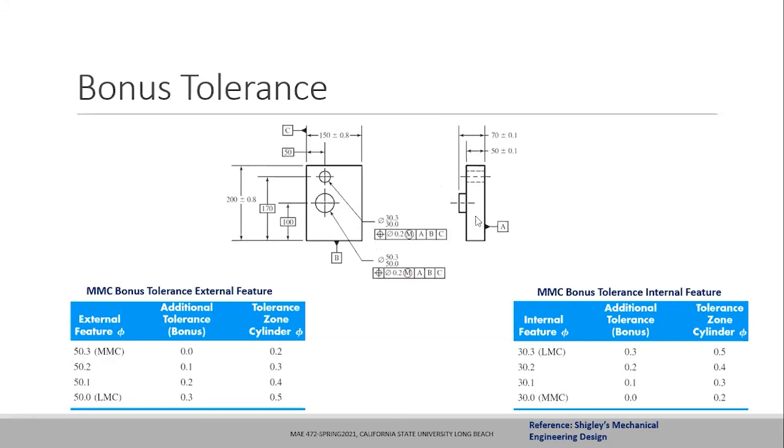Everything else in this drawing you can already figure out, whether it is this length or this size dimension, datum C here, datum B here, and datum A at the back. These are the basic dimensions: 100 from the bottom, 50 from the left-hand side, similarly 170 from the bottom and 50 from the left-hand side. Theoretical dimensions to locate the theoretical center of the hole itself. I'm sure you can figure out the information in this feature control frame as well.